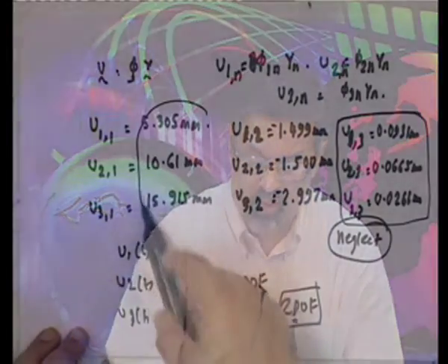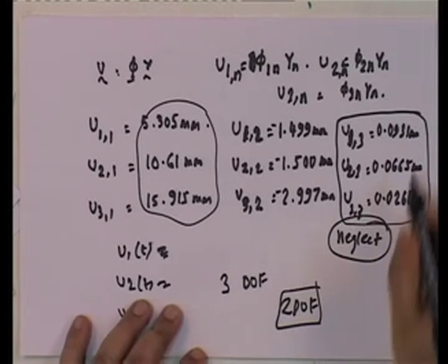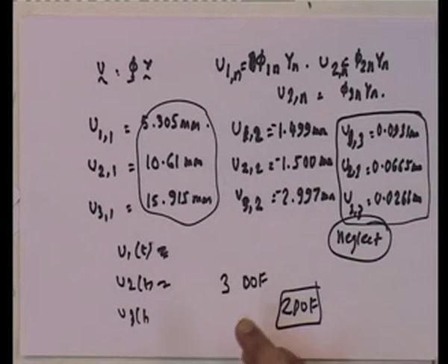If you look at any arbitrary kind of load, you will always see that this is the extreme situation in which this contributed significantly purely because it is dynamically more excited. Okay. If you do not have that situation, the total will almost be given by the first mode. Here I actually caused a situation where the second mode contributes more, I made it. However, you still see that the third mode is to be neglected.